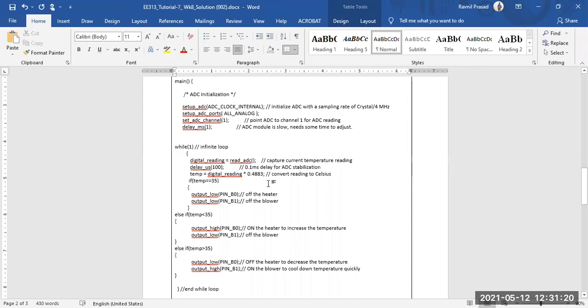Basically it is scaling down whatever reading you are getting. In your case, it can also be scaling it up or down. So don't focus that much on this particular calibration. Most of the time, it depends on whatever reading you have. You take the reading and plot it on a graph, and then you see, are you getting the expected result from that reading? Based on that, you calibrate it.